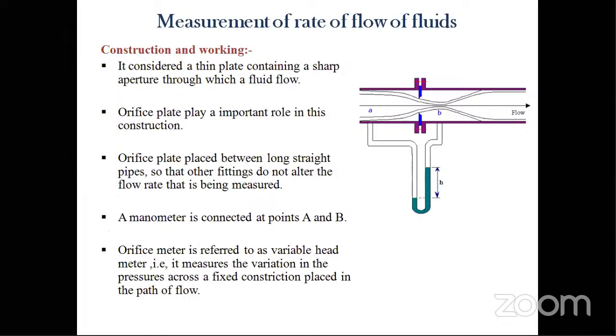Now, the construction is basically glass or stainless steel. In the case of laboratory scale, a glass instrument is required, and on the large scale in the pharmaceutical engineering industry, it is made of stainless steel, because a large capacity of liquid is used. As already discussed, when liquid passes through the orifice meter, flowing from u0 to A, the orifice plate plays an important role in the construction.